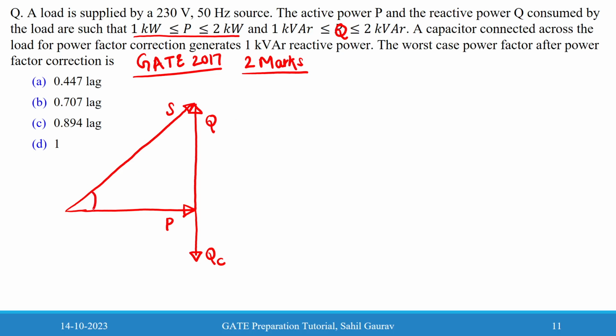We all know this is power factor angle phi. So we can write phi is tan inverse of tan. Is QC upward or downward, sir? QC is downwards. In many textbooks you find it written like this, correct? But it is better to consider this side. Here you have taken Q positive, that means lagging reactive power, and QC is negative, that means leading reactive power.